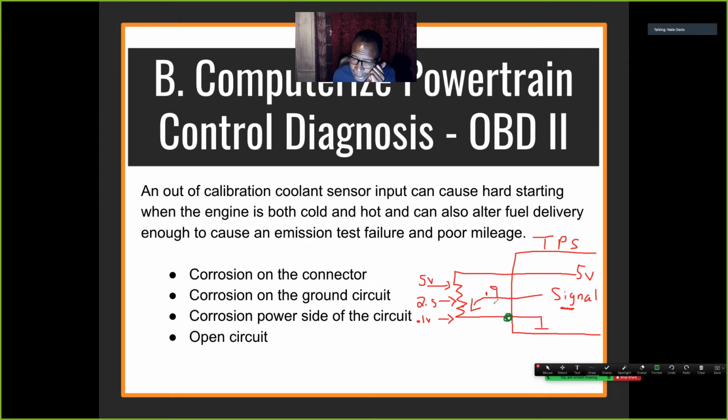You get it? Yeah. So it needs to supply more voltage to push the current through the resistor to ground. Remember, Ohm's law says it takes voltage to push current through a resistor. So if I add additional resistance, I need more pressure to push the current through it. So it's never going to go up, because remember, this line right here is doing a voltage drop.